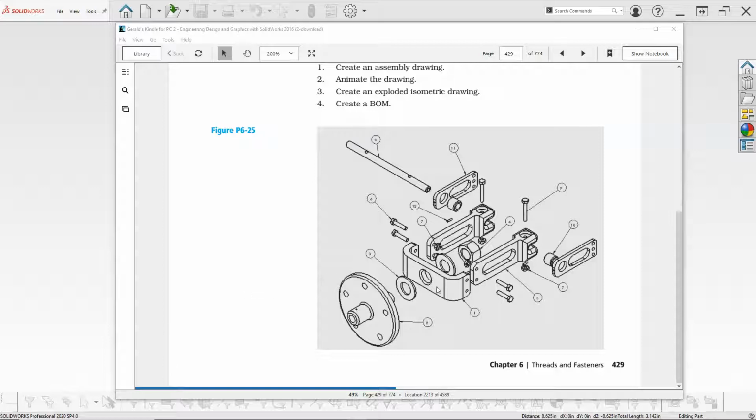Okay, so looking at the assembly, the bracket really is kind of our stationary point that everything else attaches to, so that's kind of my first inclination. And that's one of the reasons that I wanted to have the configuration so that I could switch between the machined part and the fabricated sheet metal part. And then we'll bring in the two arms. We'll go ahead and set up probably for the pivot shaft, so then we can align the support arm and somewhere in there get the wheel support in place.